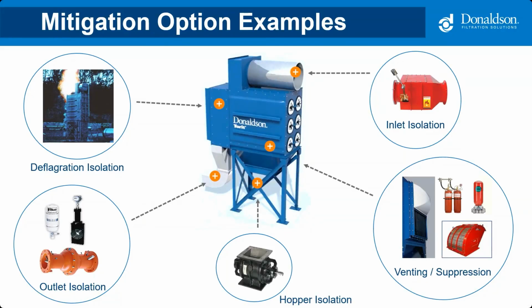This is done typically with a mechanical isolation valve, but chemical isolation systems are more prevalent in the battery manufacturing industry. Deflagration isolation: our DFE collector was independently tested, and the filter successfully isolated the deflagration and allowed no flame or spark to pass into the clean air plenum. This is an important consideration when returning air back into the facility. It may help you eliminate a high speed abort case.